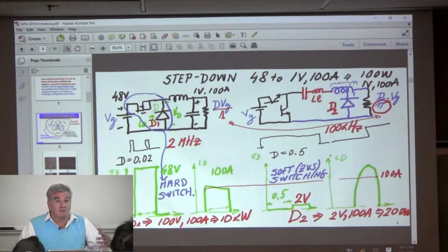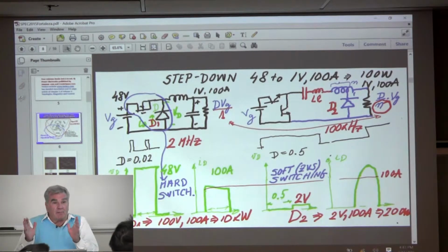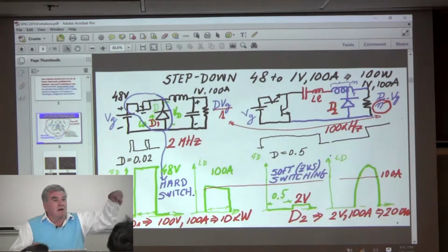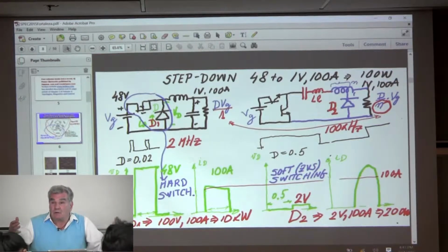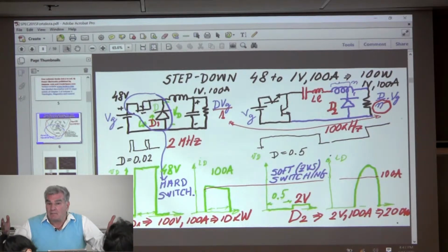So-called leakage inductance, which represents flux which is not coupled between primary and secondary, but is closed in itself. And that causes a problem that is proportional to L i squared of this leakage inductor. Every cycle, times the frequency, you make losses. So it becomes, by definition, lossy.